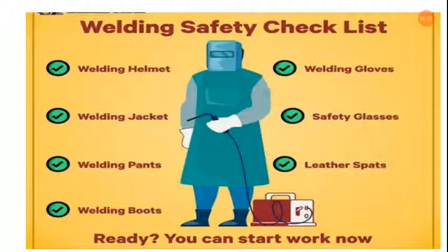You should use plywood, rubber mats, or other dry insulation to stand or lie on. Keep your gloves dry, even if this means keeping an extra pair.